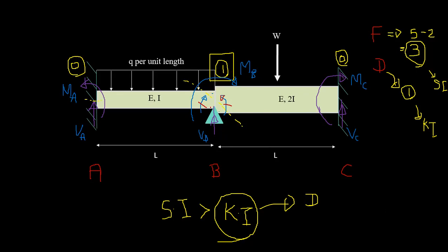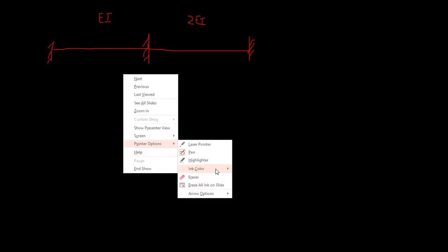And we have a value of theta, right? So first thing I'm going to do is to make the primary structure. So this is very easy, right? So simple beam. So I'm going to fix this. Only difference is this is EI and this is 2EI, right? So I write it here. I don't need to draw as it is, right? So why did I fix here? The unknown displacement was theta, and I make sure that it is 0 for the primary structure, the loading, right?